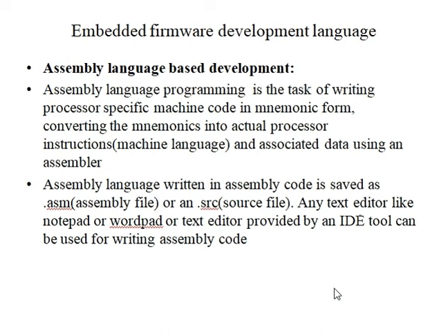So it is here 32-bit, and some instructions are 16-bit because we are using Thumb-2 flavor. Okay, so the procedure we follow here for designing a firmware, we are supposed to use either a text editor, or we can use WordPad, and we write a program in it. And since we are making use of assembly level language, you can use a tool for ARM Cortex. You can use a tool named GNU ARM Embedded Toolchain, or simply remember ARM compiler toolchain.